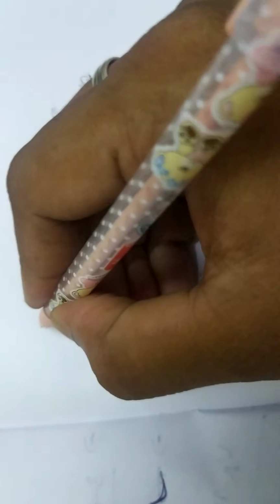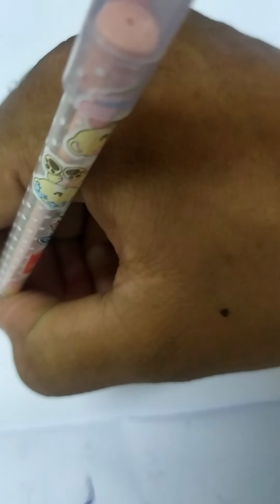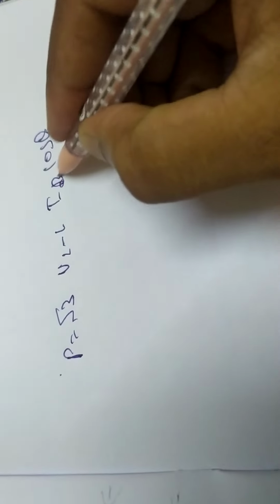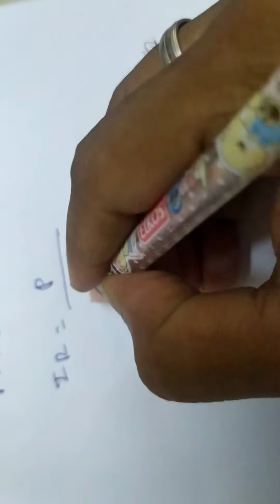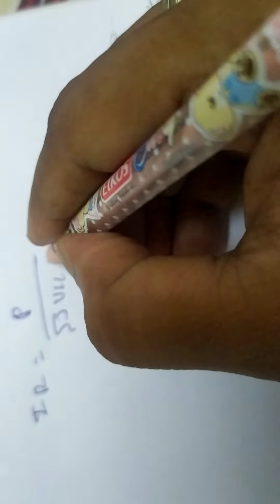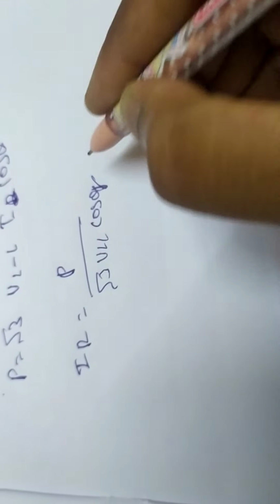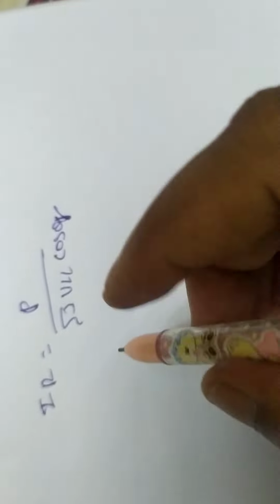From that you can get root 3 equal to V line to line IR cos phi. So with respect to the voltage, the formula will change, IR cos phi R. So if you want to calculate IR, it equals P divided by root 3 VLL cos phi R for that one. So here from all these